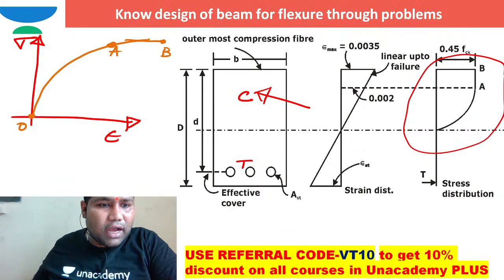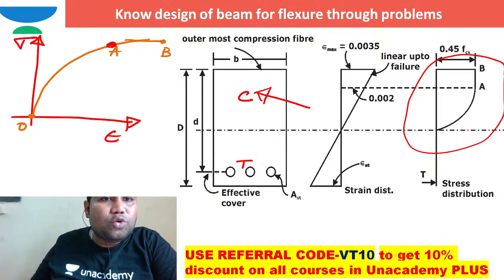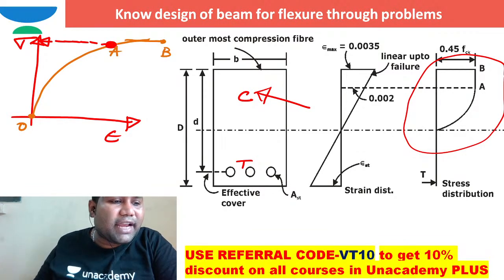Some people will ask, sir, what is this point A? What is this point B? How can we define that? This is the point A at which you can observe on the testing machine the first crack on the cube. So it is the stress corresponding to this point A where there is a possibility of first crack in the concrete cube. The point at which the first crack happens is called the stress at first crack. Can I write that? So this is the stress.